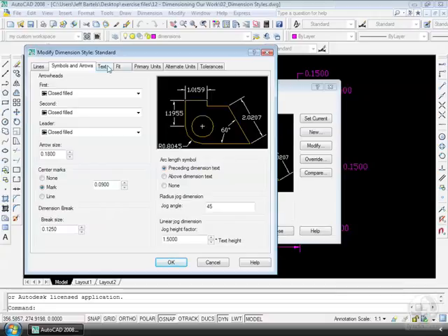The first way is to come up to your little question mark button and click. Remember, this is your help feature. If I click this, AutoCAD puts the question mark on my cursor, and I can take it to whatever setting I wish and click, and AutoCAD will tell me everything I need to know about that setting. That's one way to learn what the settings do. Let me hit Escape to clear the help text.